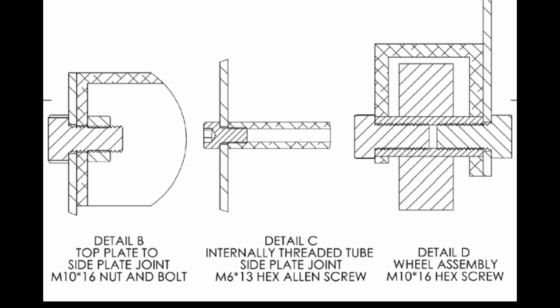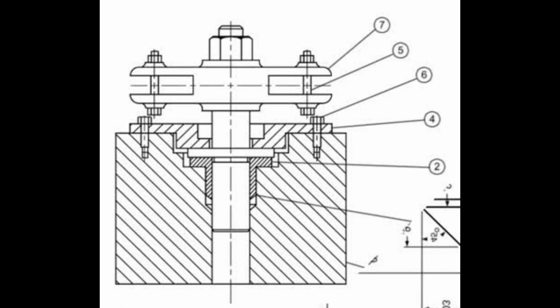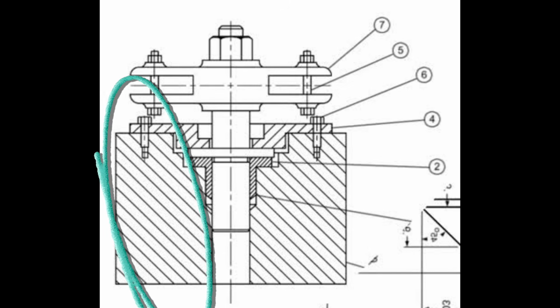Now, when it comes down to cross hatching, if you look at what BTEC provided, they've got all different types of lines. If you are going to work to drawing conventions, then your cross hatching is only done at 45 degrees. The bigger the part, the bigger the space between the cross hatching.